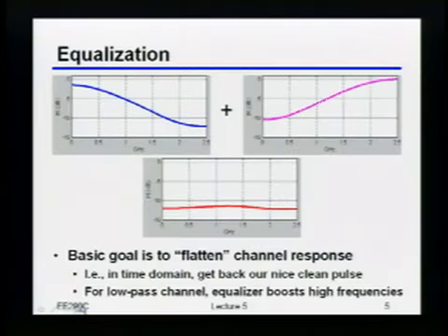So what are you going to do? Well, of course, you're going to apply the simplest thing you can think of, which is if you have something that's doing something bad to you, do the reverse of the bad thing, and then hopefully on the net get something that looks okay, right? So that general process is what's known as equalization. And it's called equalization simply because it's trying to make it so that all of the frequency components have the same response. And if they all have the same response, that means it's a wide bandwidth thing. It means you're not distorting in time the thing that you sent.